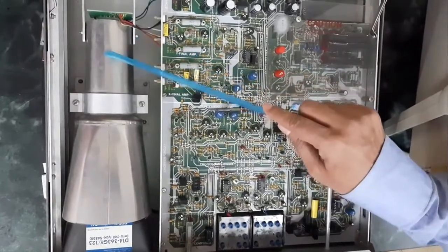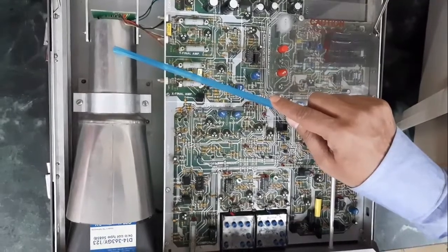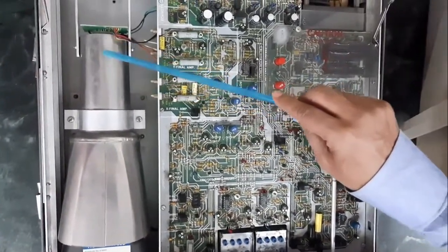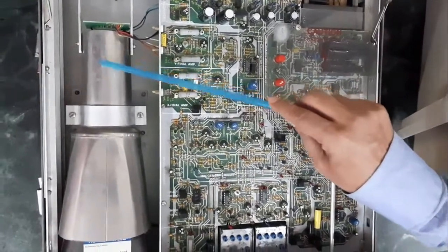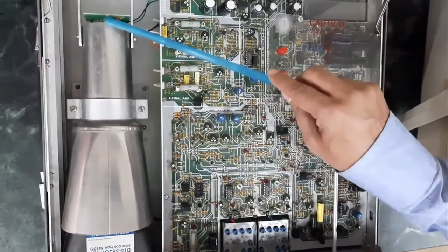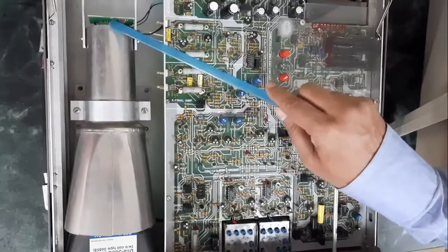So this whole section of the electron gun assembly, as well as the vertical deflecting plate, horizontal deflecting plate, as well as pre-accelerating anode, focusing anode, and accelerating anode, are only available in the tail part of the CRT, and that section is only the size of 2 to 3 inch only.